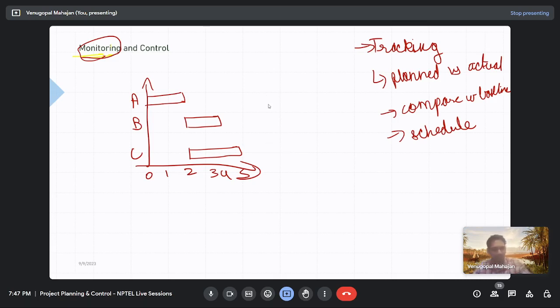But as per the planned schedule, at the end of the second day it should be 2.5 or 2. But in actual, from the site report, it is coming 1.5. That means we are delaying from the planned. From that we can compare it. So can you plot that value, the one that you got from site, on this bar chart, by converting it?